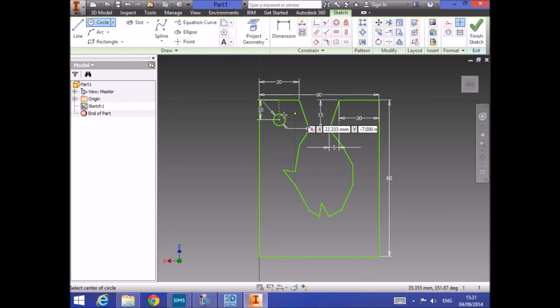Now we could go on and use perhaps the mirror tool or some other tools, but we're just going to keep it basic to do it this way first of all, to get a bit of practice with the tool. So again, I'm going to come across 10 and go down 10 like this, and produce myself another circle on that cross point, remembering to turn the construction lines on and off, and do the same again for my other 2 circles.